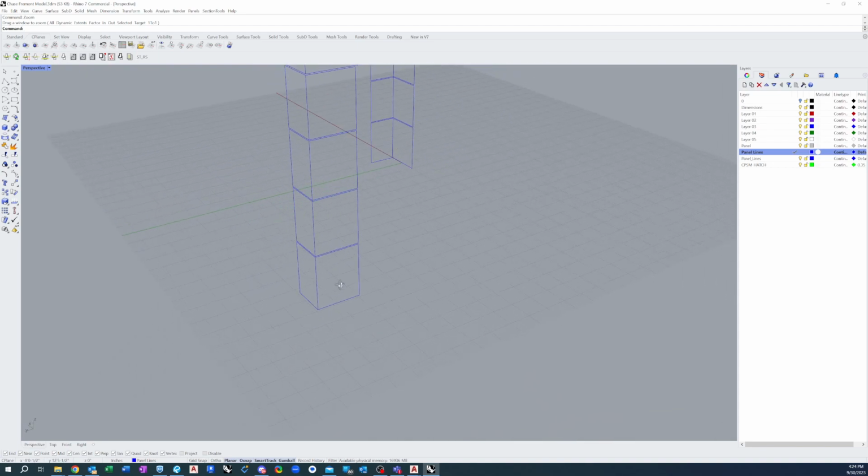So the next thing we're going to do is start building surfaces and add our return legs on our ACM panels, and then make them so they can unfold and be ready to cut on the CNC. So I'm going to start with this bottom panel, and once I get the legs drawn, I should be able to just copy them up and stretch them.